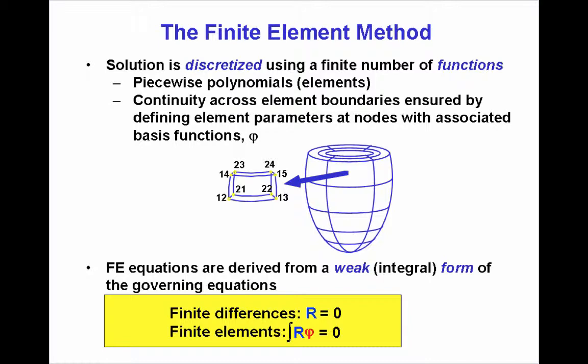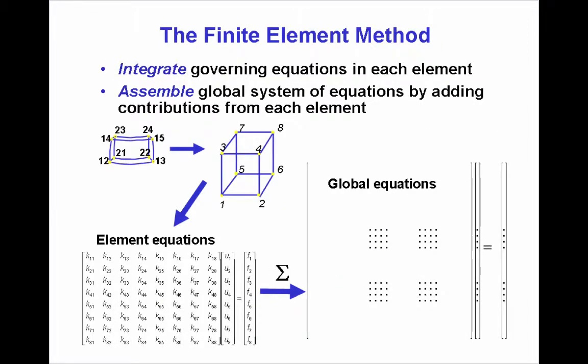The governing equations are represented using a weak integral form that gives rise to sums instead of differences. This facilitates the finite element assembly of the global system of equations by addition of the element matrices representing the discretization of the integral equations over each subdomain.